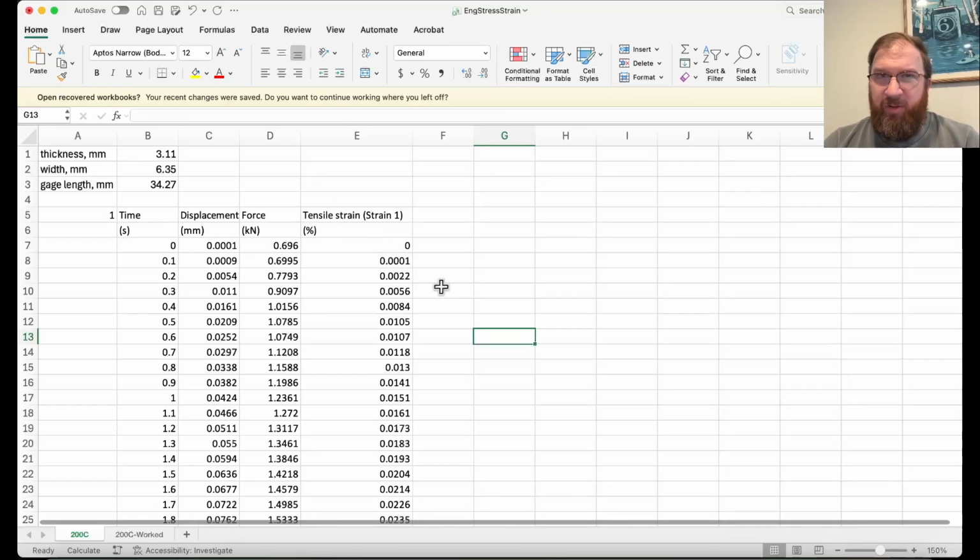A little bit about this sample, if you want to know what it is. This is a 4140 steel, an alloy steel, 4000 series, with 0.4 weight percent carbon. This is used for bicycle frames and so forth. It's very strong, so we can use less of it. It's got a good strength to weight ratio. And how this has been processed is we heated it up, formed austenite, and then quenched it, and then we tempered it at 200 degrees Celsius. So that's the process.